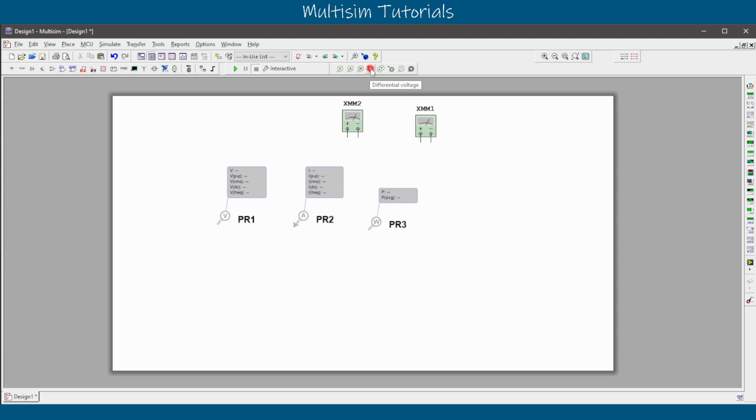We also have a voltage differential probe that actually gives two different probe lines. So when you place one down, you'll automatically get the reference probe as well. And so you'll place that around a component if you want to see that one. So that is an option. It does have some moments where it doesn't work as well as we would like it to. Outside of that, you also have an amperage voltage probe, and so that's going to give you both of these first two in one component here. And the last ones here are just voltage references and digital references. So if you want to see a high or a low on your digital system, you can use that one as well. These ones look a little bulky when you first get them out, especially this amperage voltage probe.